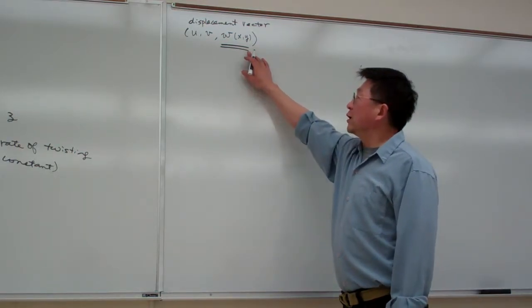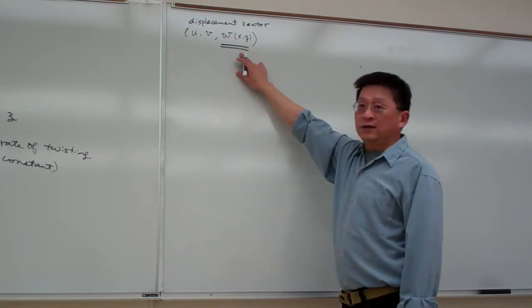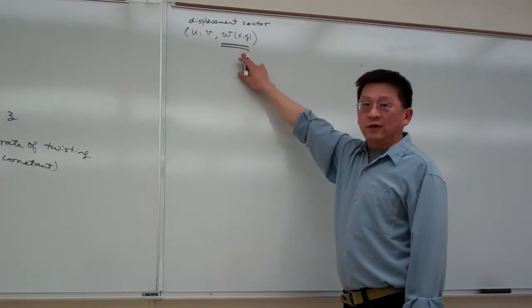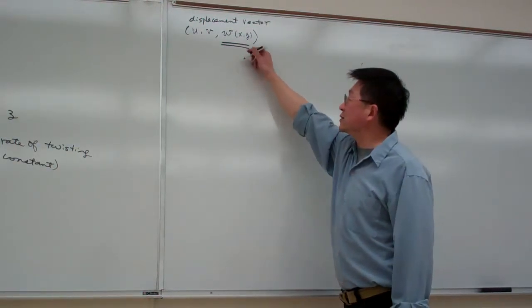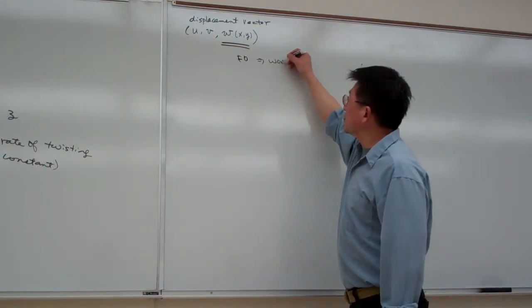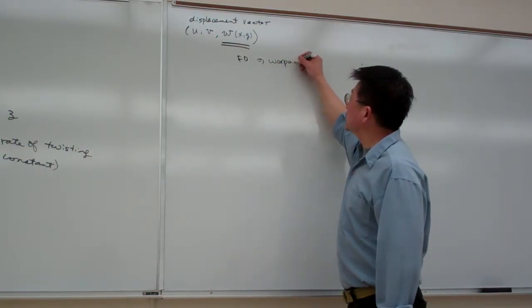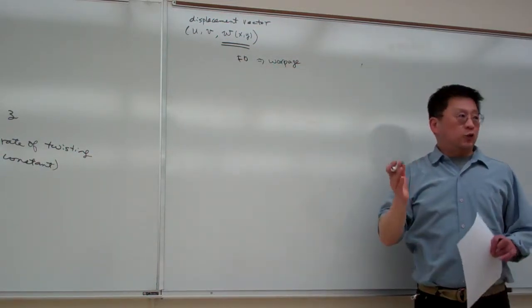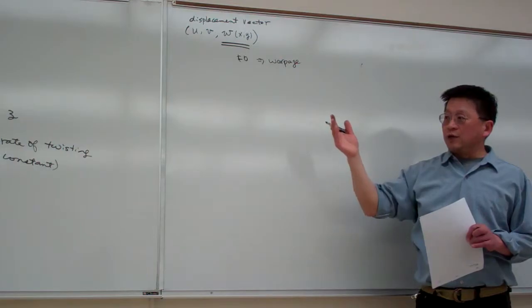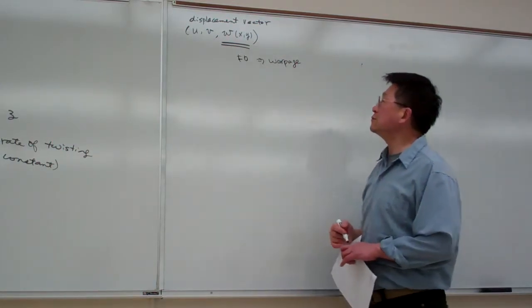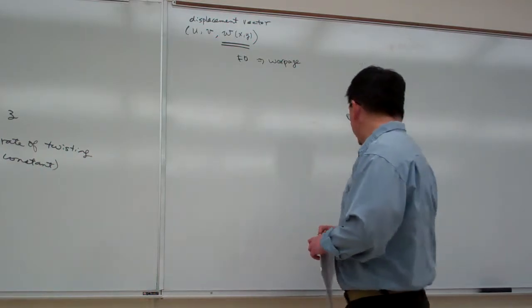Warping, or warpage, means a non-zero component, a non-zero displacement in the z direction. Again, when w is not equal to 0, that is called warpage. W-A-R-P-A-G-E. That's a special term describing the distortion of these cross sections in the z direction. So keep this in mind.